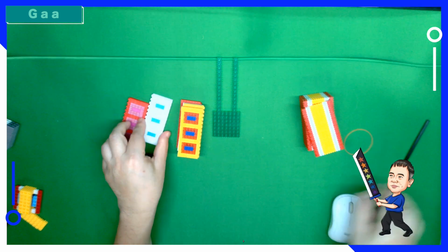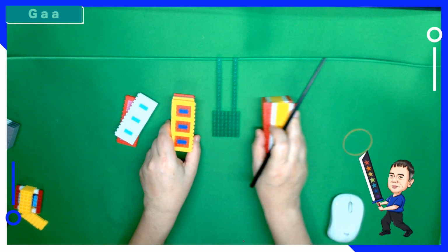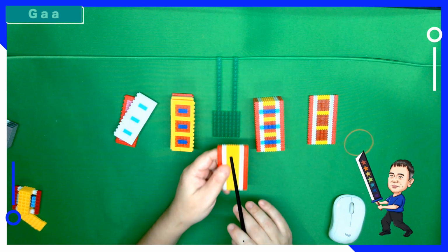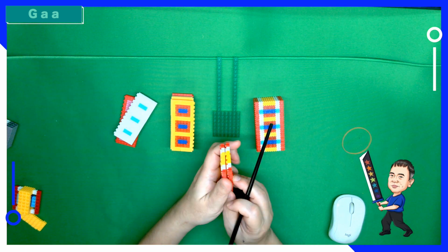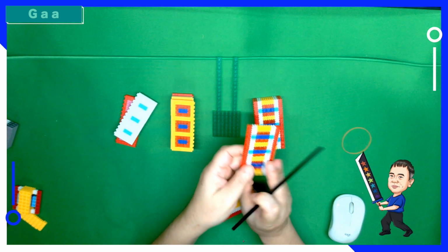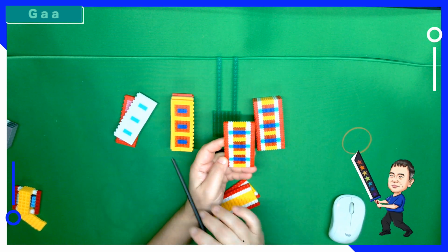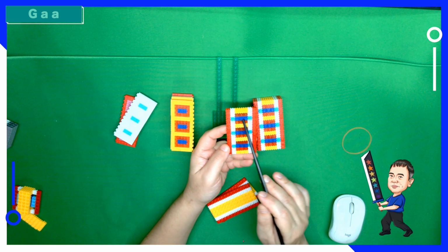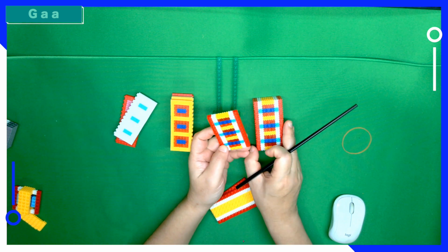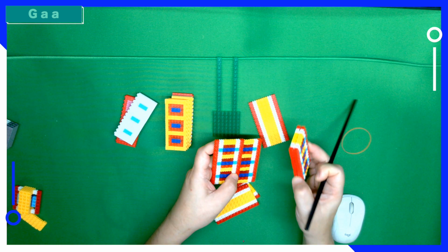Okay, now that's what it looks like, the gate all around. If I slice in a different direction, the gate from the top plate affects the channel through this outside layer, and the source and the drain and the bridge. So here, compared to this one, you can see bridge 1, bridge 2, bridge 3 between the source and the drain. If I slice a different direction, that's what it looks like.